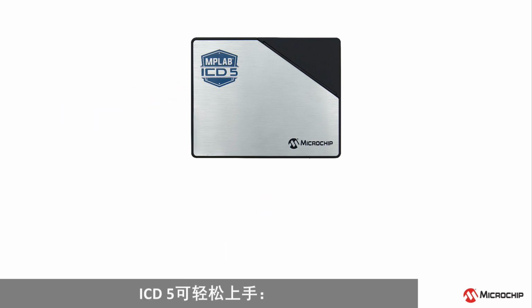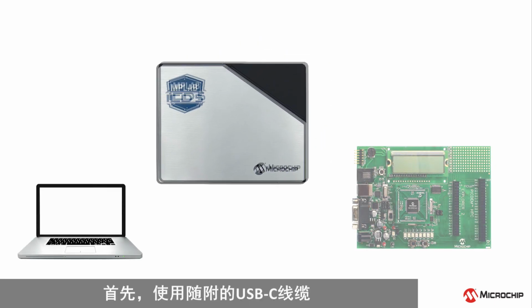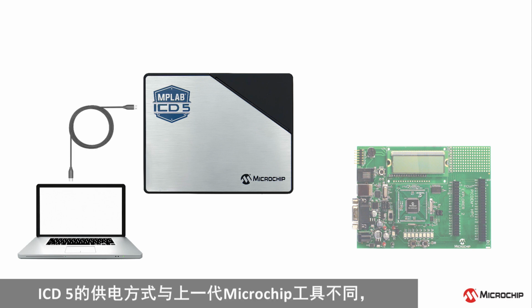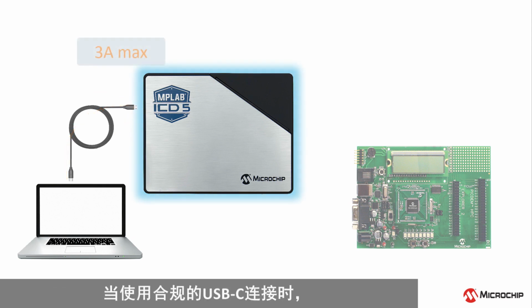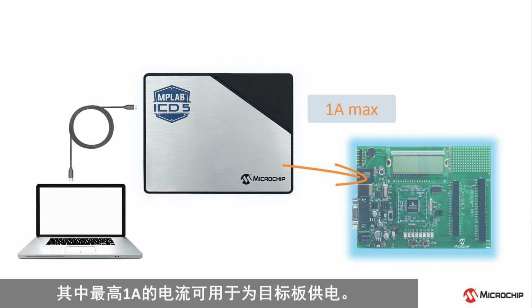Getting started with the ICD 5 is easy. First, connect the ICD 5 to your host computer using the supplied USB-C cable. The ICD 5 obtains power in ways unlike previous generation Microchip tools. Power can be obtained through the USB connection to the host computer. When using a compliant USB-C connection, 3 amps is available to the tool, with up to 1 amp being made available to power the target.